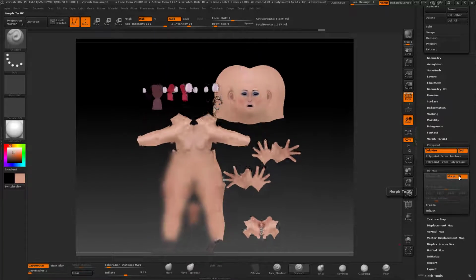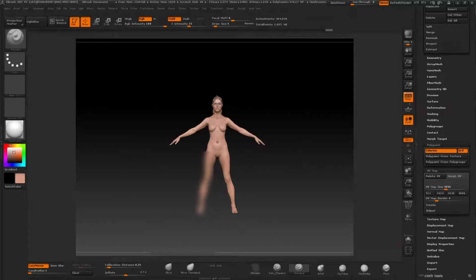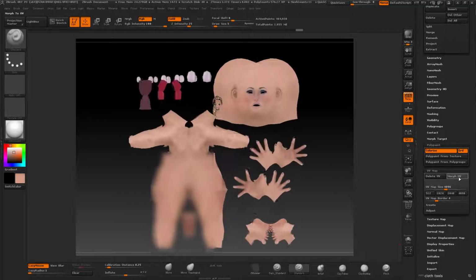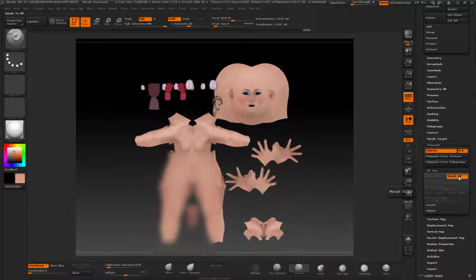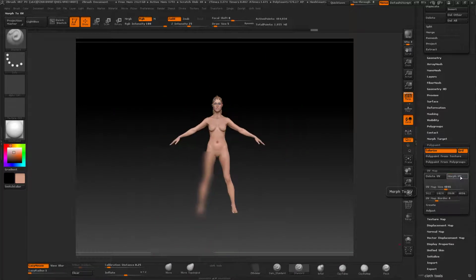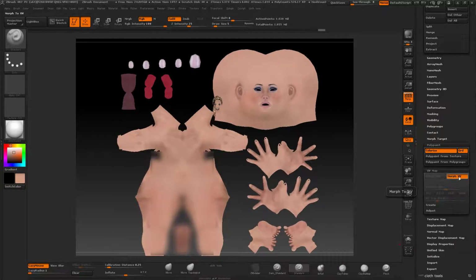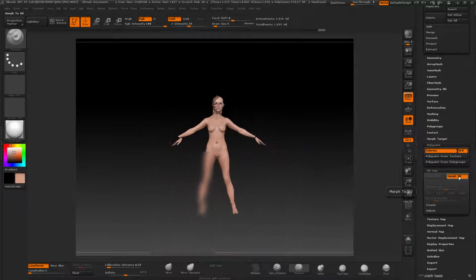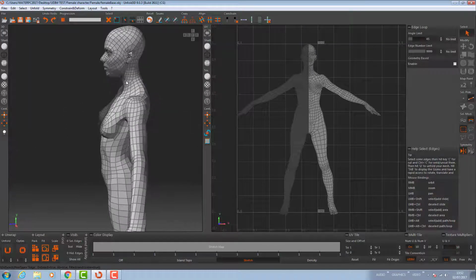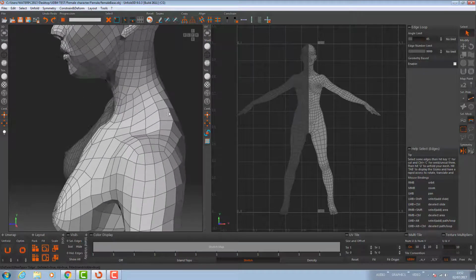To re-emphasize, in 3D we aim to do a similar job. We need to flat pack our 3D model into what's called a UV map. In 3D modelling we must first carefully plan where to cut by selecting seams. This is where we have the edges of our model. We can loop around an area such as the neck or the wrist to create a cut which will separate the part of the UV map and help us get a better flat pack overall.